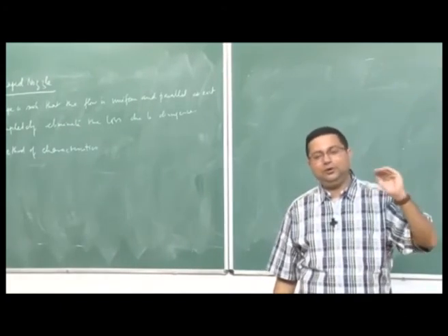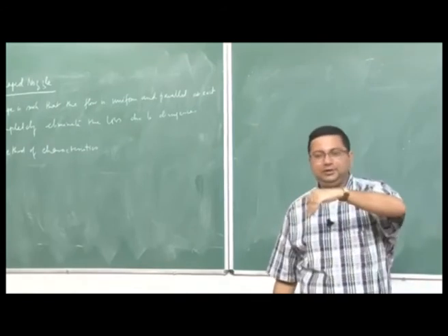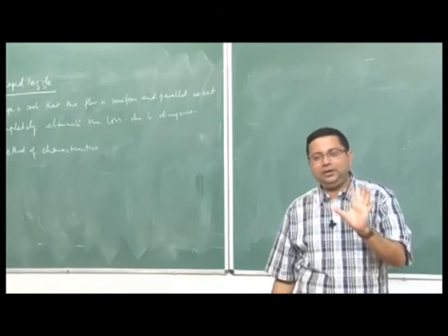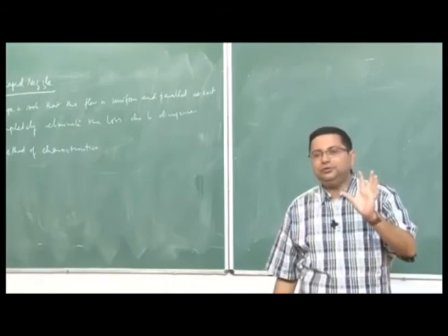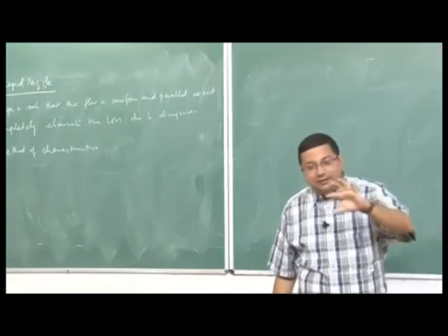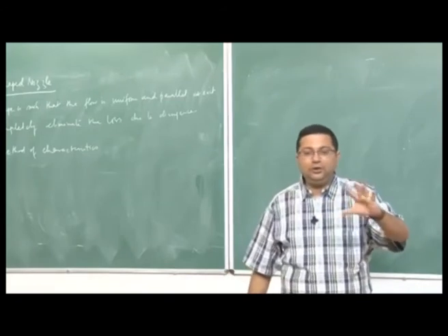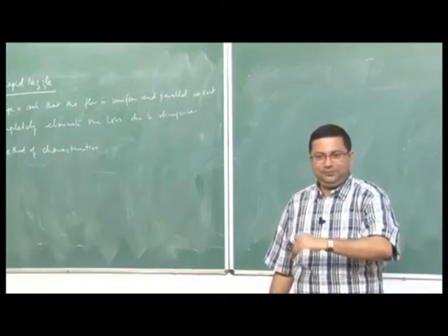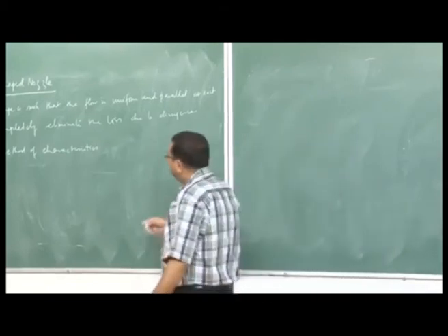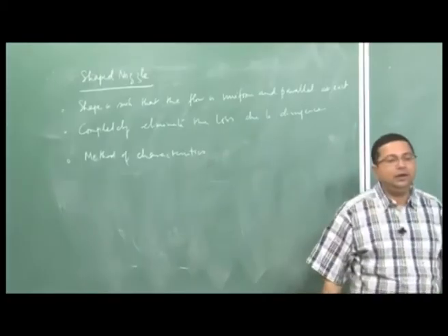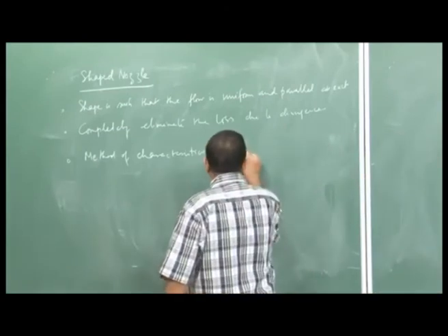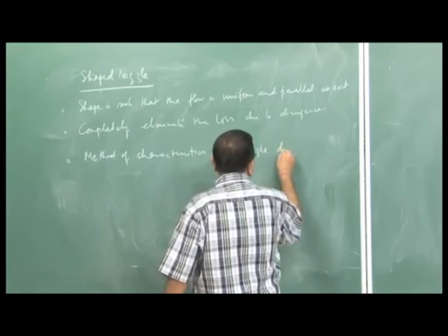When the supersonic flow goes through a curvature, it turns, and then we use method of characteristics, because that assumes the flow to be isentropic and maintains the isentropic nature of the flow. At the same time, it will accelerate the flow. Okay. So, that is the method we can now use for nozzle design.